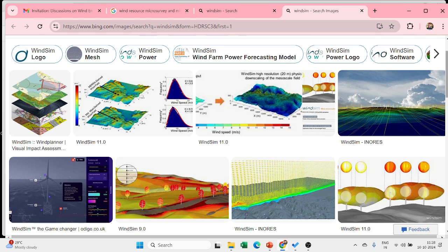If you fit it to a Weibull distribution, only two parameters are required: the scale parameter and the shape parameter. What is the shape of the bell curve, and what is the magnitude of the maximum possible wind. C is almost the mean wind speed, K is the shape factor. These two parameters define the wind speed distribution at any given site.